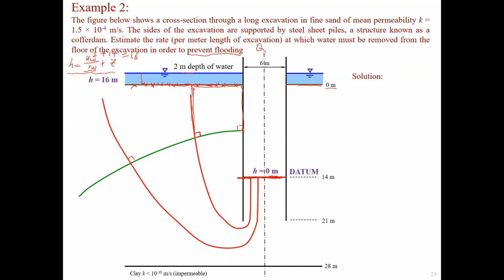We have to meet the requirement. They have to be at a right angle, and also it's roughly a square area. So we follow the same way. You see, that's the right angle. By the way, this is the impermeable part, the steel, so that's the impermeable layer. And this part is permeable soil. So obviously, this will be a flow line. That's why flow line and equipotential line form a right angle, and we try to make a square shape. So that's why I add another equipotential line here at a right angle.